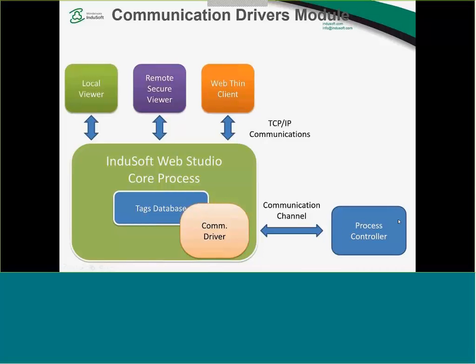So the driver module on InduSoft Web Studio works this way. Here you have your PLC. We're going to go through a communication channel. That can be an Ethernet channel, can be serial communication, or a specific industrial network like CAN or ControlNet, DeviceNet, things like this. So you're going to connect, Modbus Plus for example, our communication driver to the PLC. We get the bytes and bits from the PLC, we process them, and we load them into tags in our tags database on the core of the product.